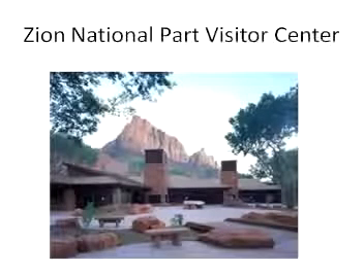The only drawback for this system? Well, of course, it uses water. So it might be something you'd like to use in a hot, dry climate, but in places like Phoenix, Arizona, there just may not be enough water that you can use this during the entire cooling season. But it certainly will save considerable energy compared to the use of air conditioners as used in traditional buildings.